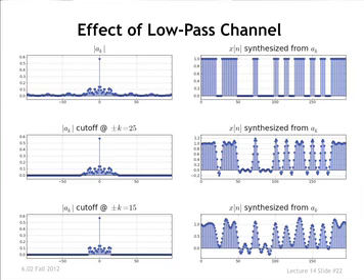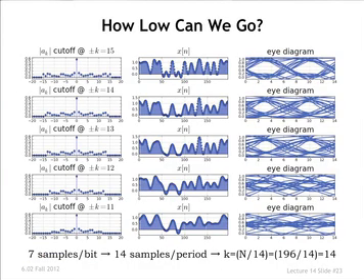This is even more evident on the eye diagram here. These are eye diagrams, again, the same kind of thing. As you successively transmit less and less of the high-frequency content of the signal, what gets received is a more rounded version of what was sent in.